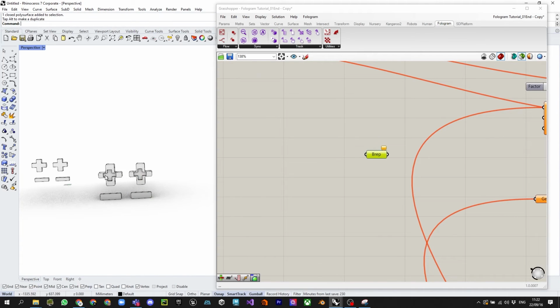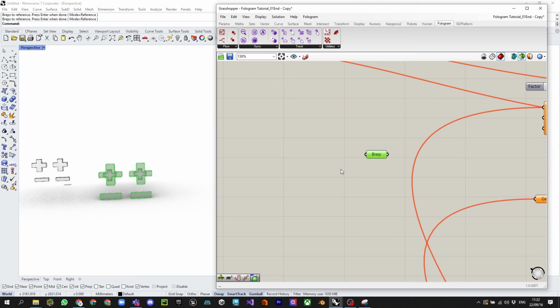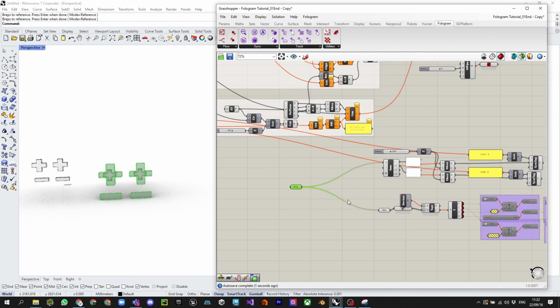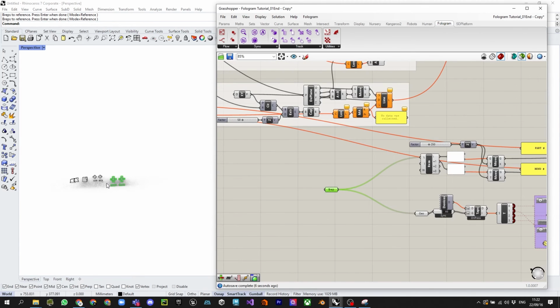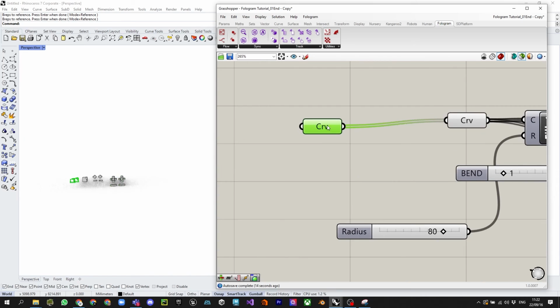You know how to sync the color now. Now select it in order. 0, 1, 2, 3, right? So go to BREP, right click, set multiple BREP, and then 0, 1, 2, 3. Enter. Okay, then it's in order. And make sure that you link it to both this thing. I'm gonna share this, but anyways, so that's it. That's how you change the button. That's how you change the original geometry, and you only need to worry about that. All right, so it's really simple.